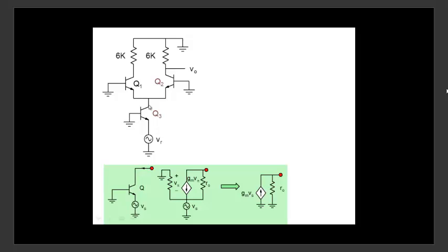Note that what am I trying to do? I'm trying to transform this new thing into what I already know, my traditional circuit here. So I'm looking down from here and asking, what does this appear as? Q3 with something attached here, what does this whole thing appear as? And I've done this over here. You can see that I can take this and write it as GMVS and R0. This appears as a current. Note that you take this, put this over here if you would like, and look at this one here and see that this is nothing.